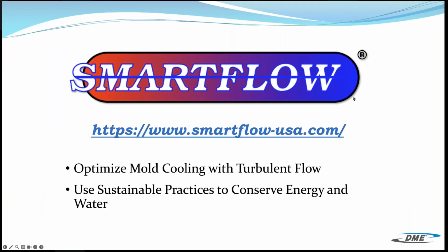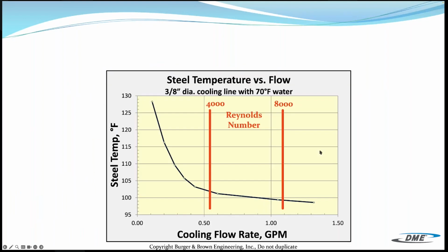So today we'll talk about the importance of injection mold cooling, and how we optimize our processes to ensure we've got effective cooling and ultimately good parts in the end. The cooling process usually makes up about 60 to 80% of your total molding cycle time. So the cooling process is very important to be optimized and efficient, to help make good parts and to reduce your cycle time.